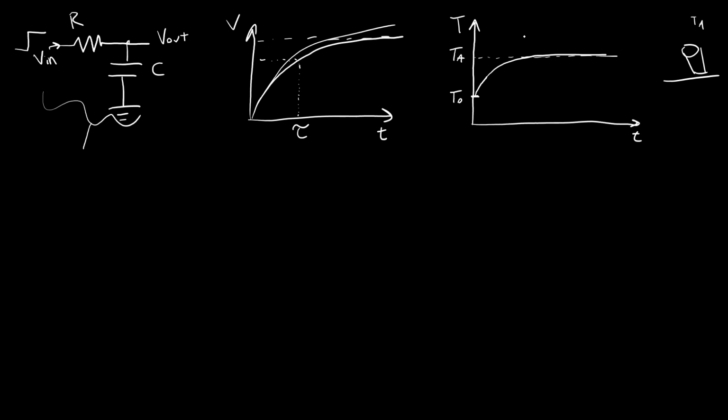It's not going to overshoot. It's not going to somehow get warmer than the ambient temperature or get warmer and then cool back down. It's just going to approach the ambient temperature. And the same thing would happen if I put, say, a cup of hot coffee on the counter that was initially at some higher temperature. It's going to asymptotically approach and then eventually reach what we call steady state, where it is no longer changing at some point in the future.